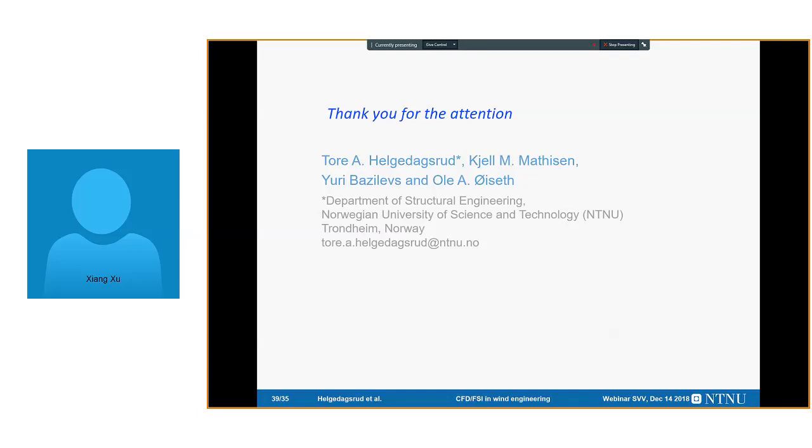Except for that, I think we have actually done a model test of this problem. Last year we used 20 plates to simulate the free surface, and carried out the model test of the floating bridge section, like what you have shown in the figure. So if you want to tune your simulation a bit, you can take contact with us. We have that data available.